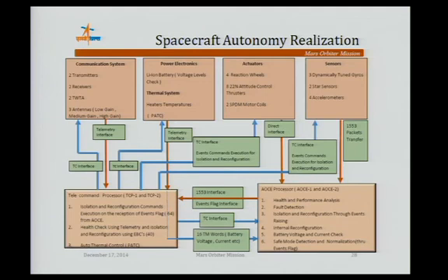Actuators: reaction wheel, thruster, and a solar array drive mechanism, which points towards the sun depending upon the command. Particularly in case of loss of lock, it automatically searches for the sun and then locks to the sun. Sensors: there are 3 gyros, that is the inertial units, 2 star sensors and 4 accelerometers. The accelerometer is used for cutoff, where once delta V is achieved, it automatically cuts off. The remaining 2 sensors are used for attitude control.